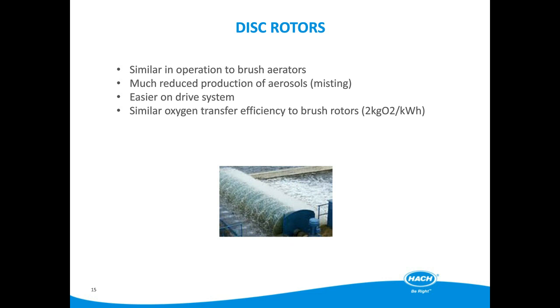Other forms of mechanical aeration are available, including spiral aerators, which impart a velocity to the water, and vertical shaft aerators, which offer higher energy efficiencies but also require mixers to move the body of water around the ditch. Currently, horizontal shaft aerators are the most common form of aeration within oxidation ditches.